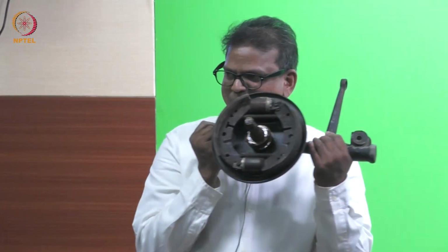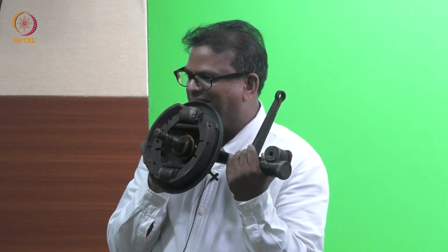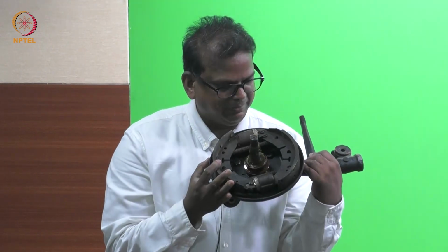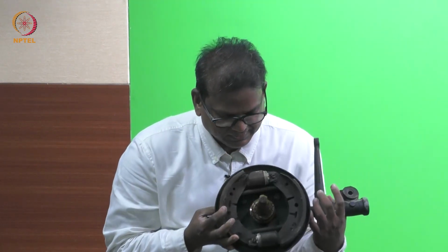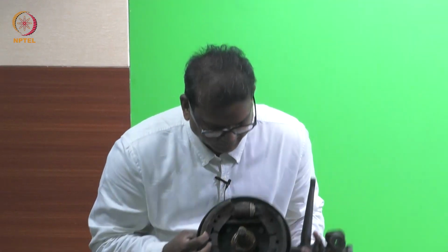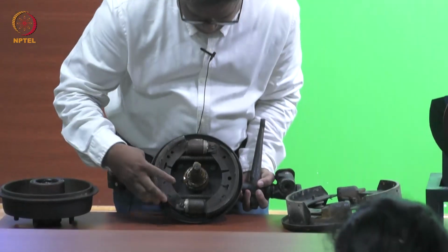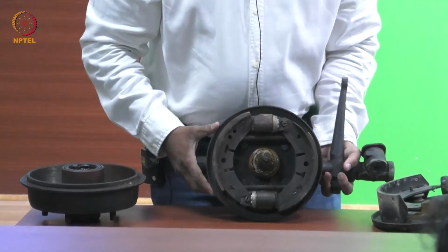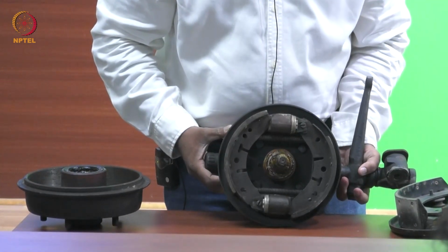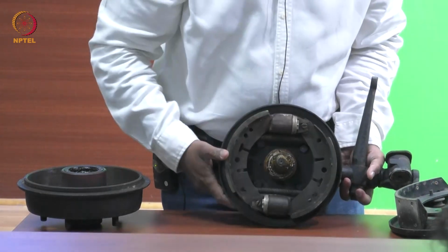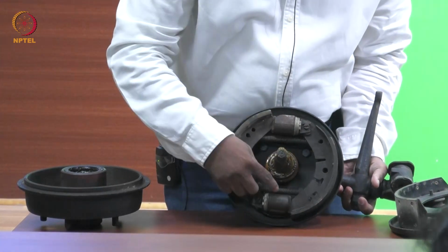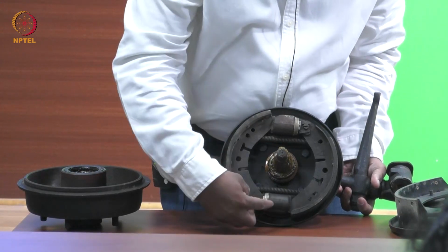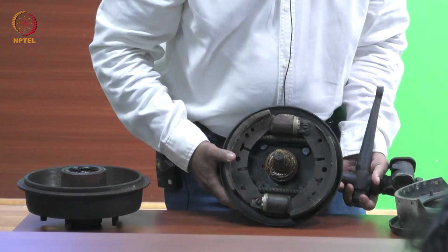It's a drum brake system. Is it leading, trailing, or leading? It's leading because you could see the two wheel cylinders are there. And again, the backing plate will be there. And you can see this is the spring for retaining. These are the springs for retract. Once you release the brake, it should come back to the original position. Whereas that one can be arranged another way, self-adjusting. That is called the duo brake system.